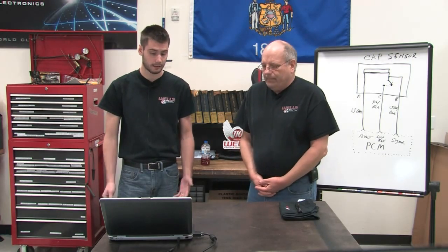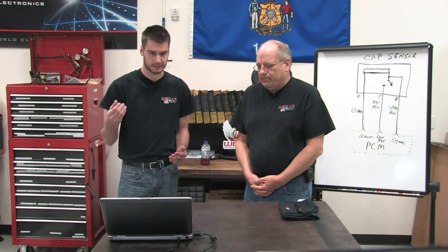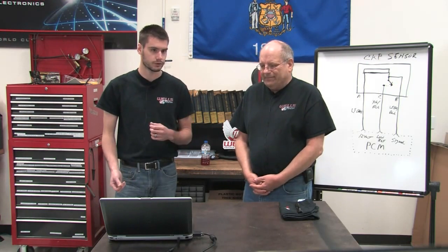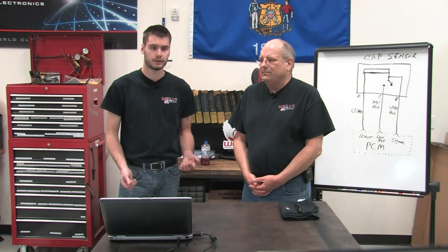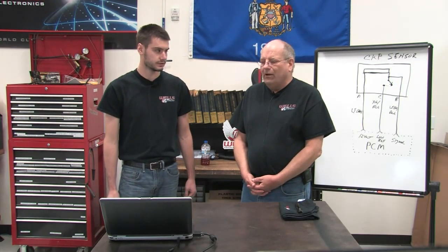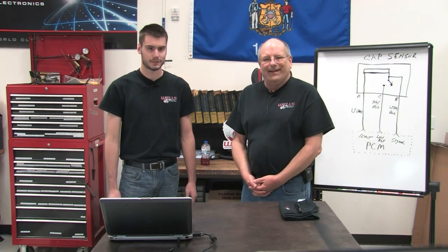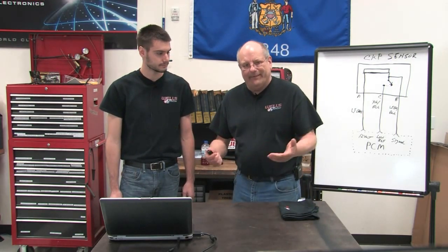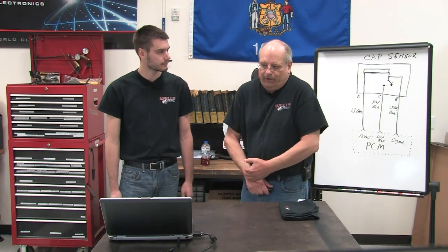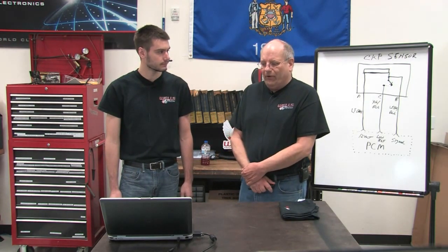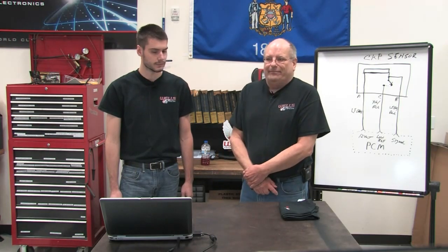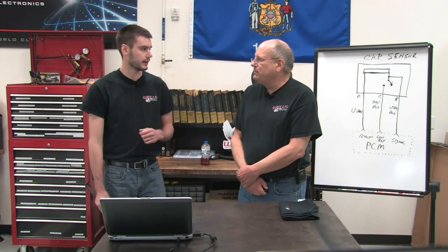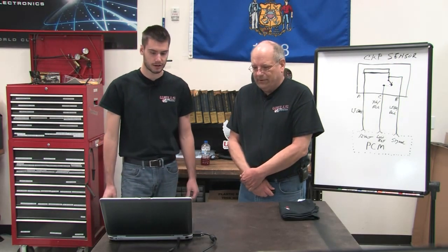I looked all over online and nobody says it's supposed to be exactly 12 volts or battery voltage or 11 volts. So we did the next best thing. We brought in a like vehicle. Somebody in the building here had another one. We checked the voltage, and how did it read? 11 volts. So that must be a known good. If you're checking it and you get 11 volts, as far as I'm concerned, that's the way it's supposed to work. We put the new sensor in, put it back on the lab scope, and it was working fine. The car's been good to go since then.